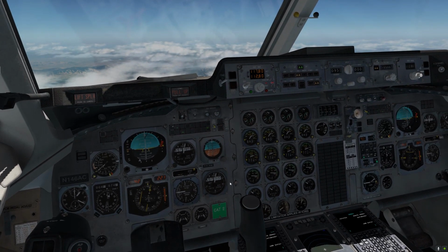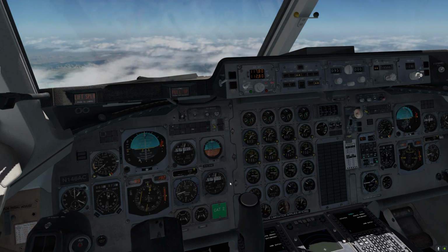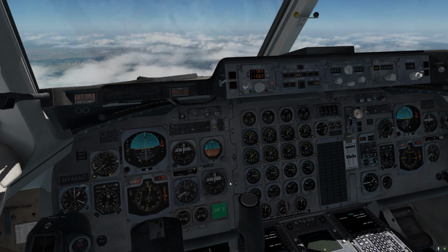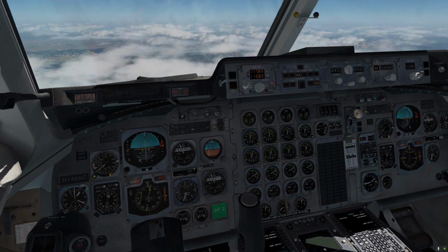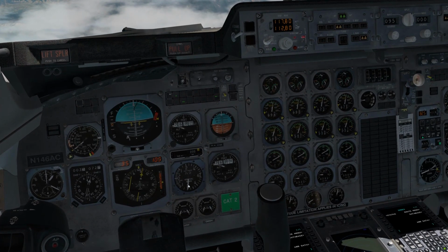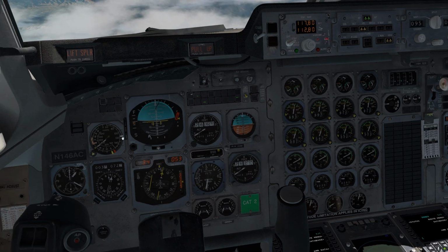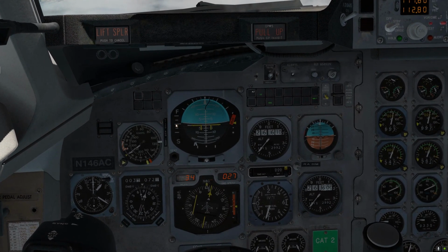I'm going to decrease the throttle, and I'm going to press and hold the sync button and let that nose come down. I'm manually pushing the nose down to about just below 2,000 feet per minute. Let go of sync. There we go. The autopilot should now hold us at about 1,700 feet per minute. I can use our airspeed bug here and this airspeed indicator to kind of set my power. I just want to maintain our current airspeed.